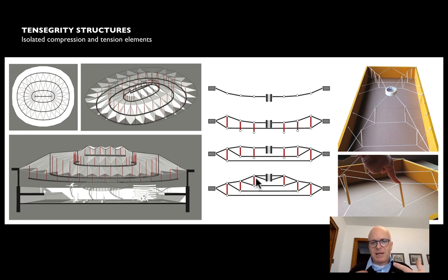And again, if you zoom out, you can imagine that the tension on the bottom is clearly doing some of the work of bending. It's these cables on the top that I think are misleading. We expect from what we know of trusses to see compression elements there. And in fact, all of the compression is being taken by these vertical separators that are turning the entire roof structure into a three-dimensional set of triangles, and therefore carrying the bearing load by channeling those loads down into the bottom rank of cables.